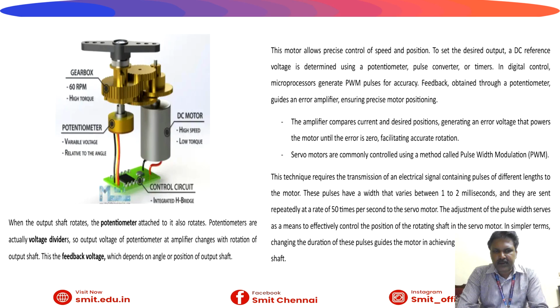Feedback obtained through a potentiometer guides an error amplifier, ensuring precise motor positioning. The amplifier compares the current and desired positions, generating an error voltage that powers the motor until the error is zero, facilitating accurate rotation. Servo motors are commonly controlled using a method called pulse width modulation, that is PWM.